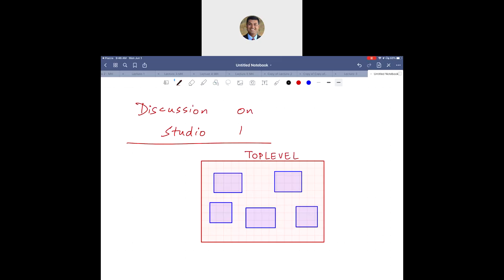So whatever you are looking at as the input and the output to the top level design, those will need to be connected to something physical in the XDC file. In this case, only 5 of them, right? No matter what you have inside of this top level, there might be 100 design files.